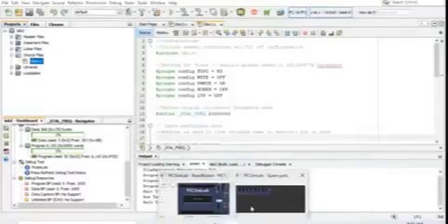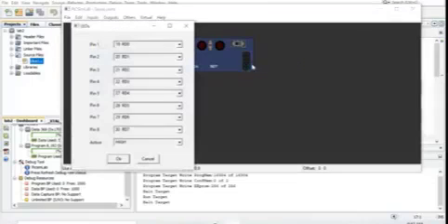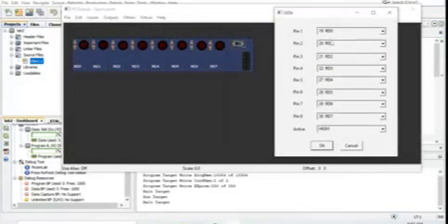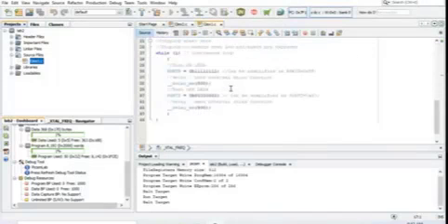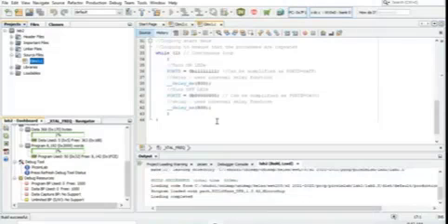Make sure that the setting here: right click, go to properties, click properties, and then everything RT0 up to RT7, the configuration must be active high. Why active high? We refer back to our program. We are writing 1 because we want to turn on, so this means that the configuration must be active high. So we start by compiling. Okay, it is a success. So we proceed to debug.